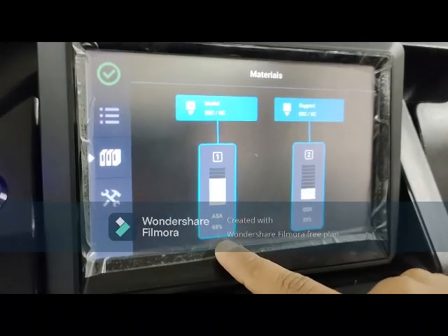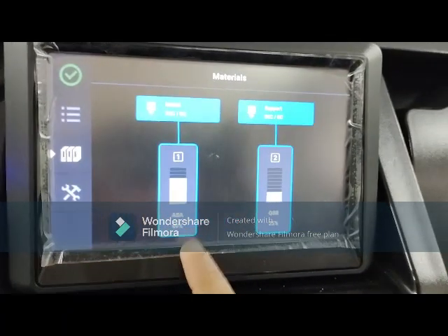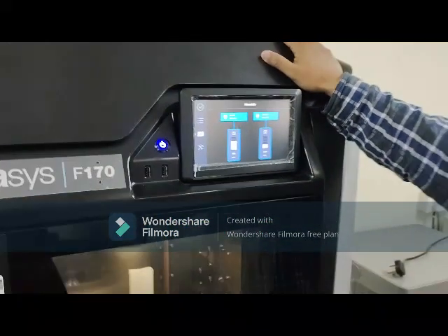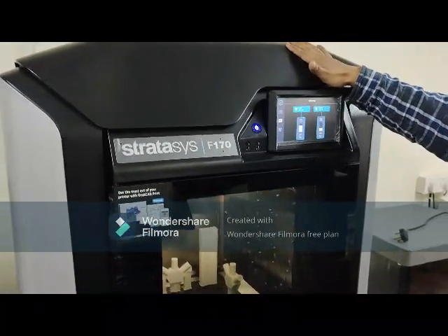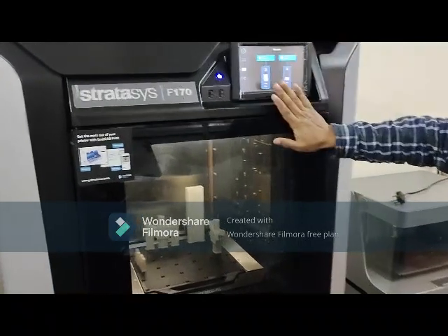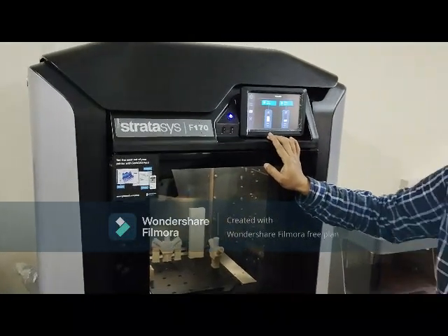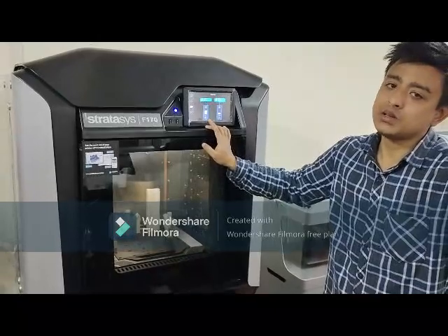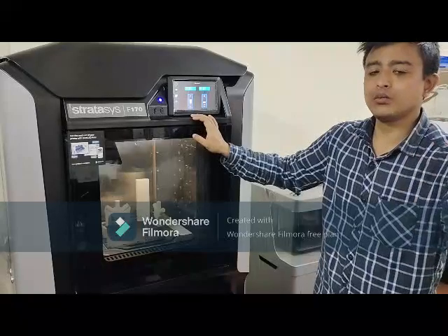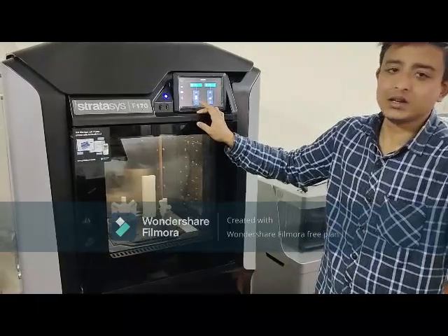Here we can see 69% of ASA. ASA is the model material we have here. Similarly we have ABS material, ASA material, PLA material, and TPU material. So in a single machine we are using 4 different types of material. That is only for this machine. In the rest of the machines the orientation and configuration are different. All these materials are thermoplastic material. Thermoplastic means that when we heat the material, we can fuse it and deposit it. These are all basically plastic material.